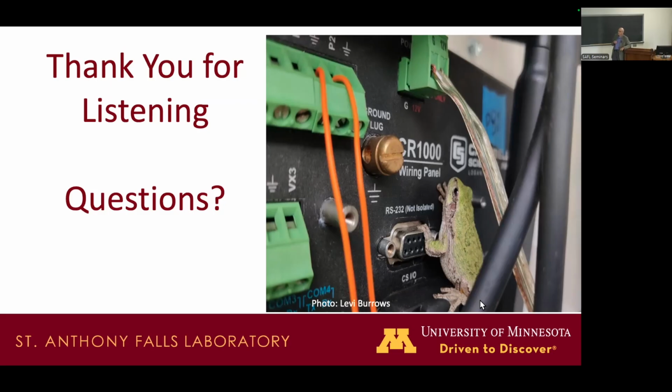So filtration is a way to remove things that you cannot remove through other means. So if you still have to get the phosphate out of it, then you want to put in something like an iron-enhanced sand filter. It is not the most cost-effective per pound of phosphorus, however. It's getting at really hard phosphate to remove.